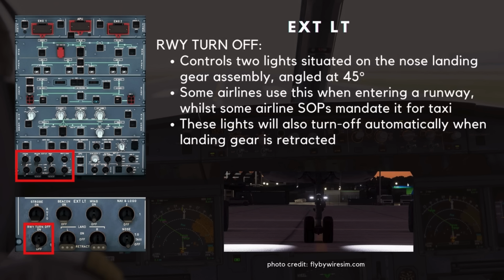The runway turn-off switch controls 2 lights situated on the nose landing gear assembly. They are angled at 45 degrees. Some airlines use this when entering a runway, whilst some airline SOPs mandate it for taxi. Check your company manuals for your operating procedures. These lights will also turn off automatically when landing gear is retracted.